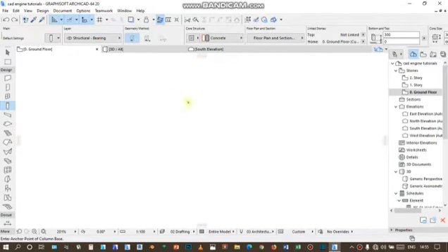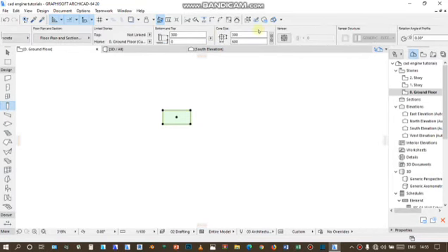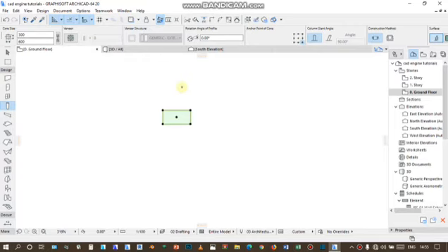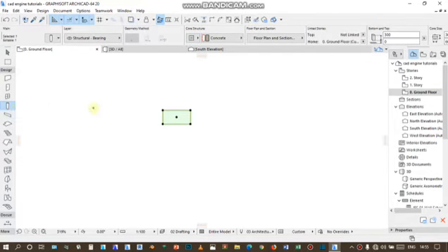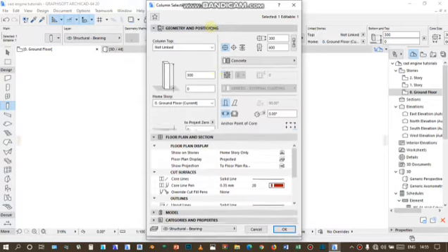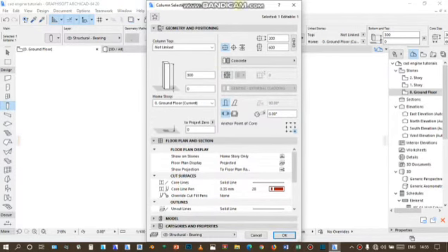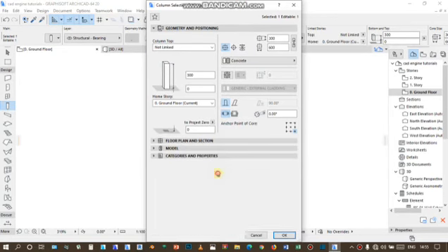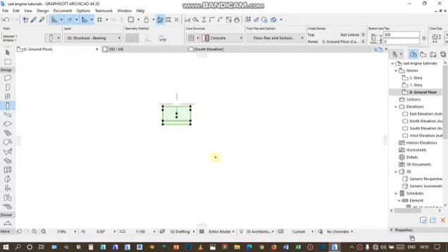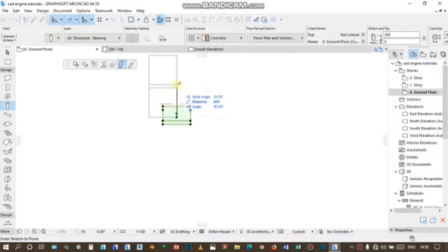So now the column has some editing, some touches that can be done to it. If you enter the dialog setting with Ctrl T, you can choose to give this column, let's just say, an angled column. Now you check the angle, let me say 75. You can later change this angle here. This is where you change the angle, like this.